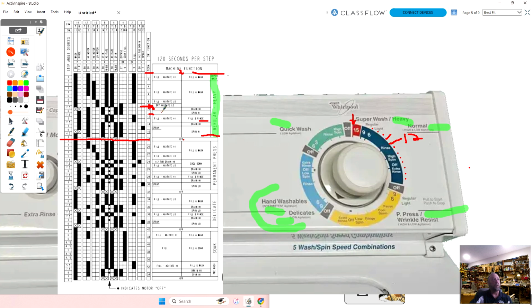So that rinse cycle is how long? It's 2 increments long. Okay? And that is going to start filling with water. Well, what are we doing from 10 to 12? We are draining and the machine's going to spin. So between 10 here and 12, the machine's going to start draining, and as the timer moves to here, it'll stop spinning, and then it'll start filling with water. It's going to agitate again until it gets to this high spin right here.